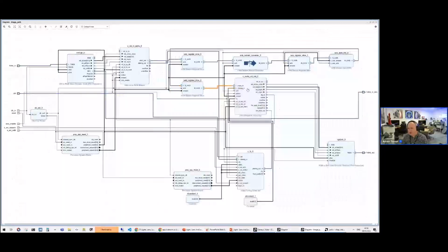And then it goes through what's called an AXI4-Stream to video converter. This takes in the AXI4 video stream, and it takes the timing information that's been set up within this video timing controller provided by the received video. And then it generates another parallel video, the parallel video going out.